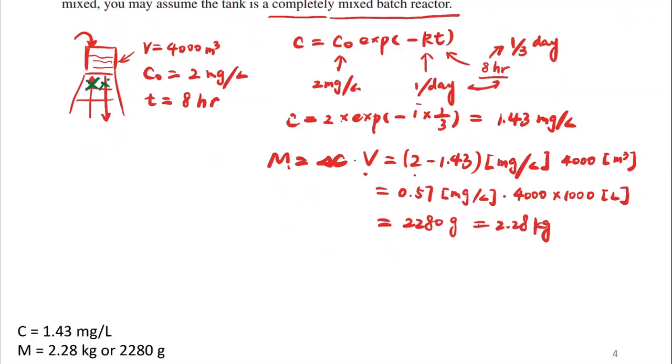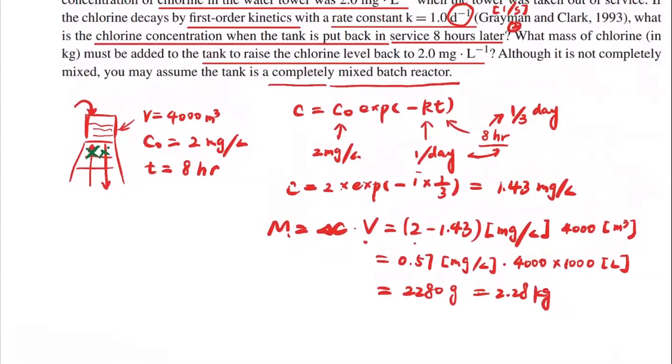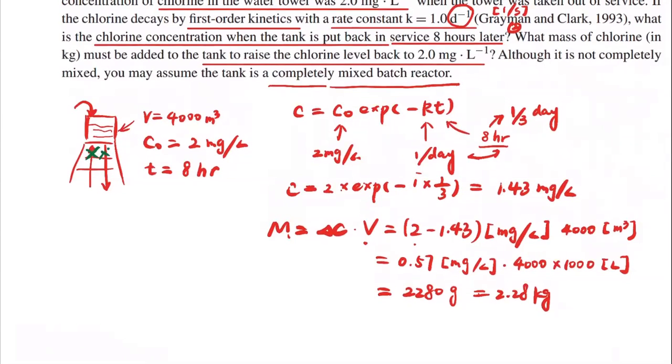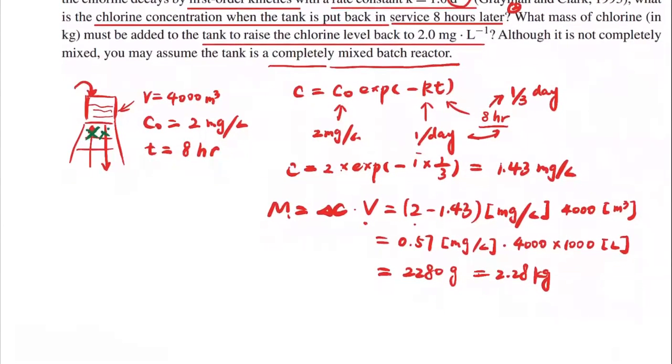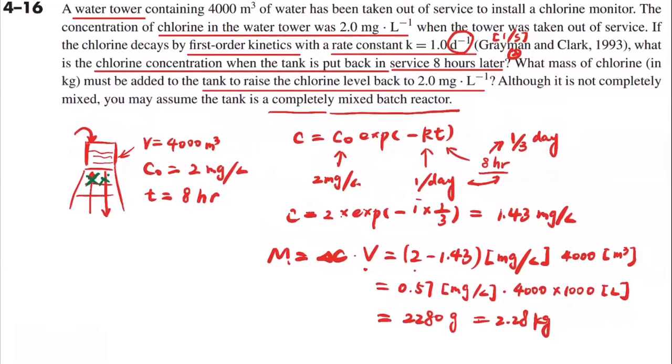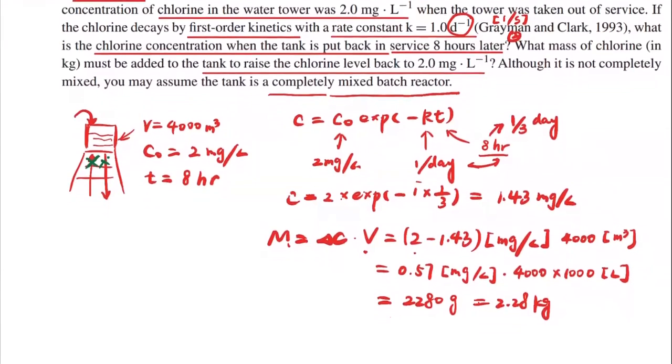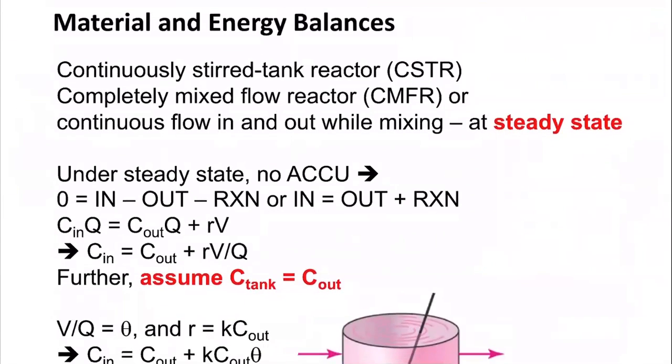Okay, so this is a simple application of this batch reactor problem here, right? As we said, the batch reactor has a critical issue for water treatment, because it doesn't have inflow or outflow, but for the treatment of the water, there's always flow going by, right? So that's why we need to introduce the flow reactors. And the first one that we can think about is the CSTR.